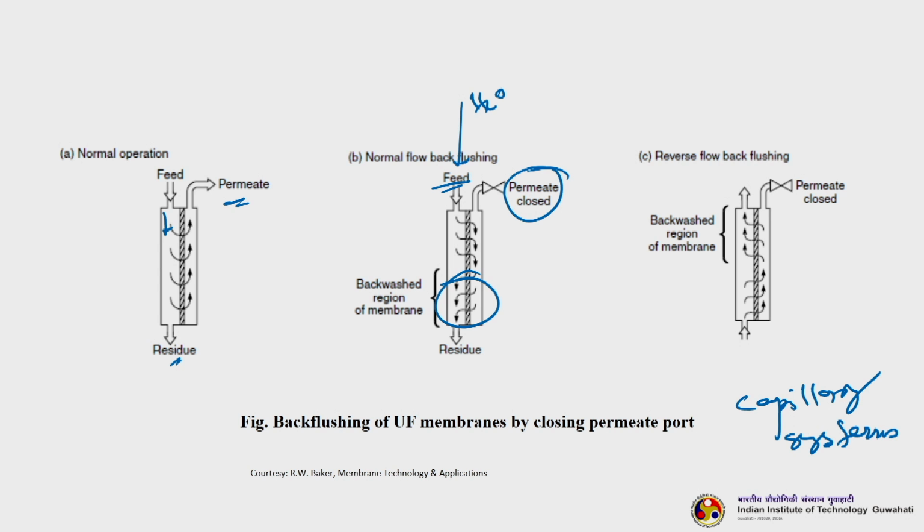This is one way. Then what should I do about the other area? Now, this is the answer. Then I reverse the flow of the water. So, instead of flowing it from the feed side, I am now flowing it through the retentate side. Then the same procedure happens, and the other half of the membrane will be cleaned by backflushing. So, this is how backflushing is done. This is for example in capillary tube membranes, and usually for any other systems also the procedure is the same.